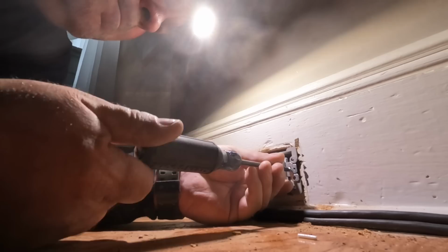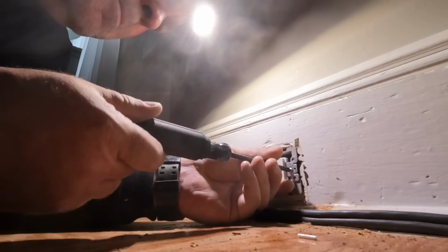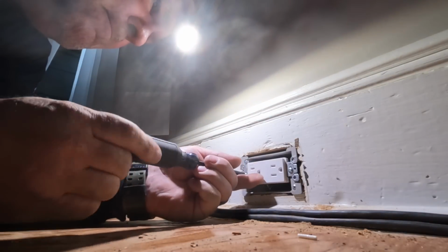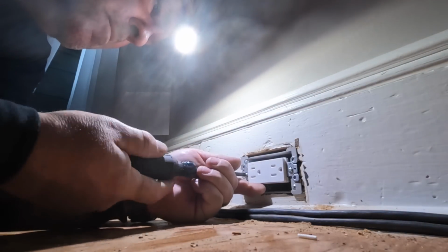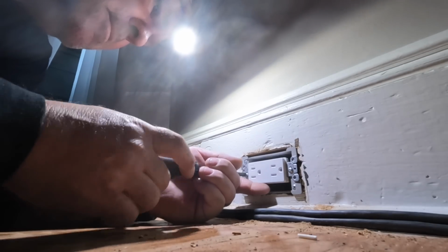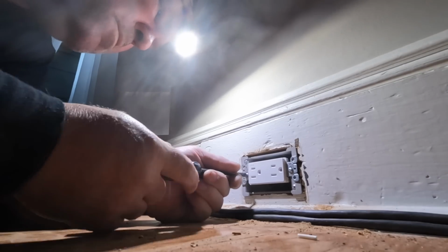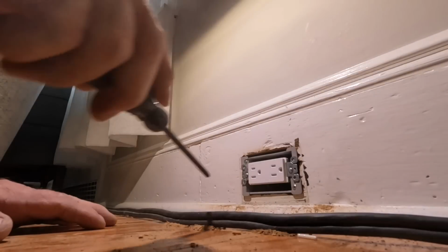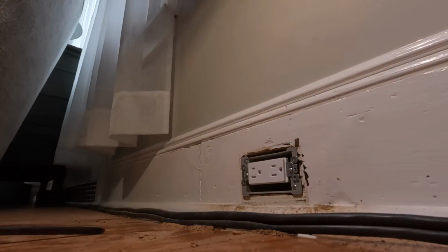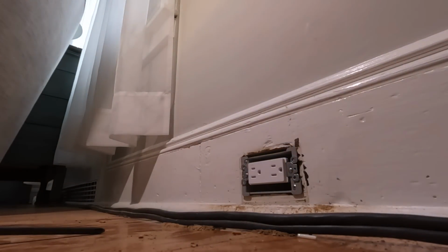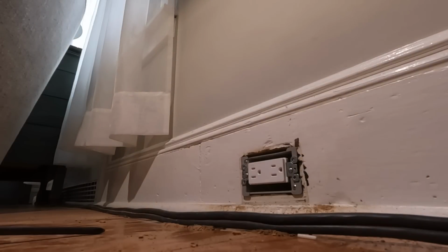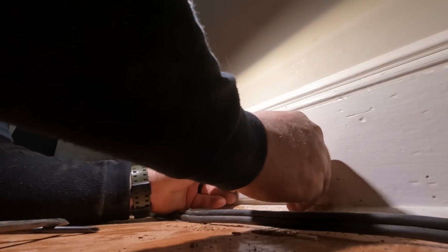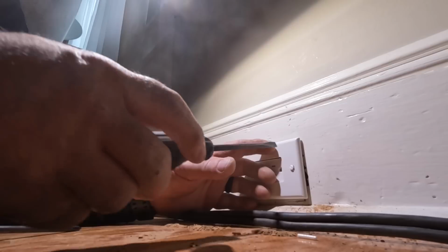Now both of these receptacles you saw me here today wiring up and installing, they still haven't been connected to a circuit just yet. I'm still connecting and still diagnosing where the knob and tube goes and how the circuit's going to go. But once I do know that, I'll come back and bring these cables that go to these receptacles into a junction box to supply them with the new circuit. And then of course it's going to have to be arc fault and GFCI protected. Not necessarily for the living room, but there's going to be some stuff in the basement that's going to be on this circuit as well. So we're going to install an arc fault GFCI circuit breaker in the main breaker panel, so this will be compliant.